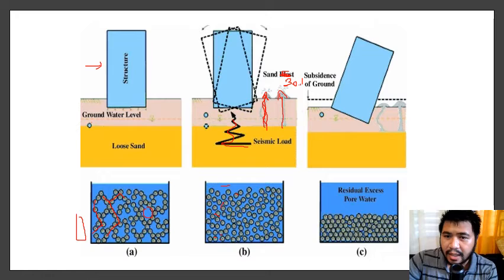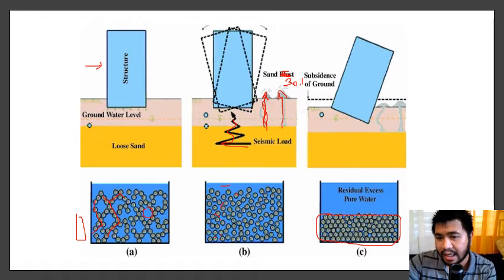And the end result here is that the soils actually end up being more dense after the liquefaction, and all the water will just rise above. And of course, during that phenomenon, your building temporarily experiences being over a soil that has no strength. So the building can tilt. It can also undergo settlement.